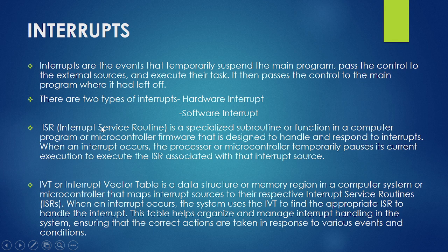As we can see, ISR, interrupt service routine, is a specialized subroutine or function in a computer program or microcontroller firmware that is designed to handle and respond to interrupts. So when an interrupt occurs, the processor or microcontroller temporarily pauses its current execution to execute the ISR associated with that interrupt source.